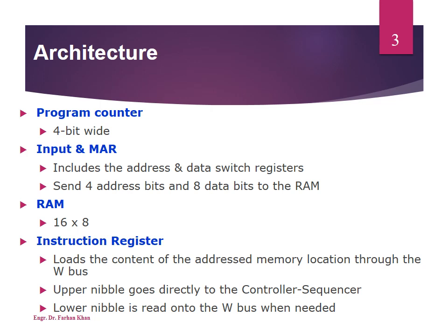Let's go through a brief detail of the SAP-1 architecture. The SAP-1 architecture is controlled through a program counter, which is 4-bit wide. The program counter counts through the different instructions of the instruction set. It can count from 0000 up to 1111, so it can point towards up to 16 different instructions. For SAP-1, we only need 5.